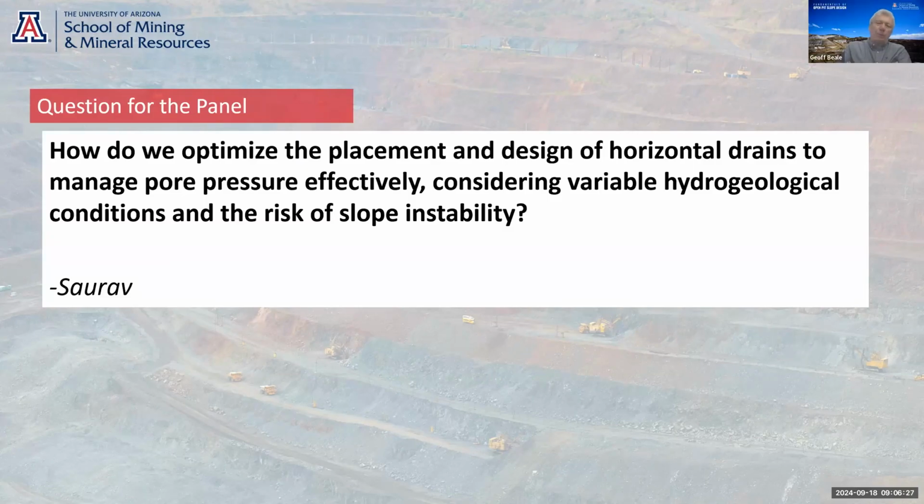Yeah, I think just to reiterate the point is you have to have piezometers, right? There's many projects you get involved with and they're drilling drains and the drains produce water, but there's no piezometers to know what they're doing to the pressure. And so the drains are clearly taking water out of the slope, but the effect on the pressure is unknown. So any optimization of the program will involve making sure you've got enough piezometers.